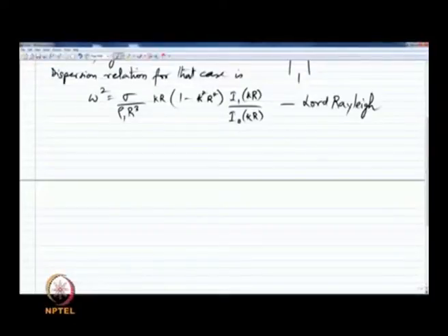And the source of this growth essentially is surface tension energy. So, a cylindrical jet that is infinitely long has greater interfacial energy in terms of the surface tension than liquid spheres that are discrete and arranged a spacing apart given by 2 pi by k bar in a non-dimensional way.